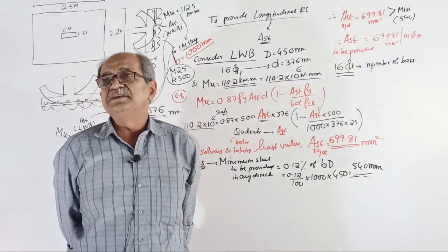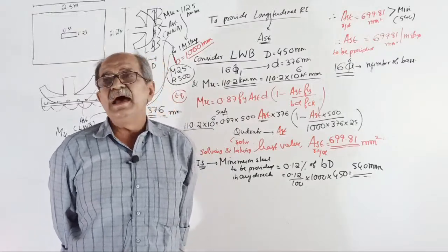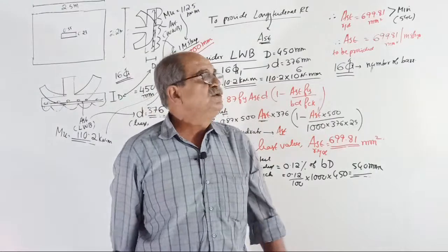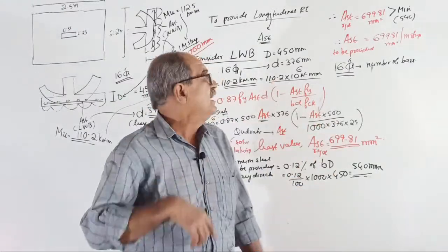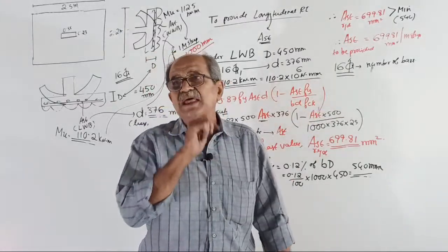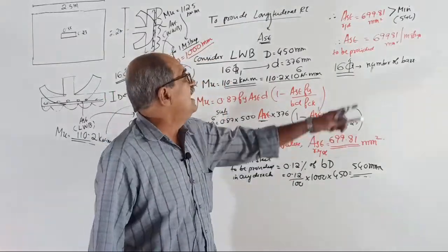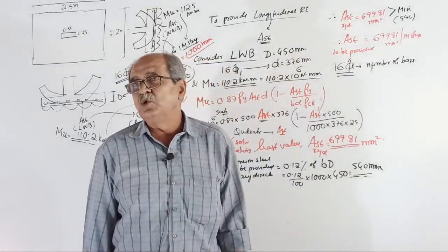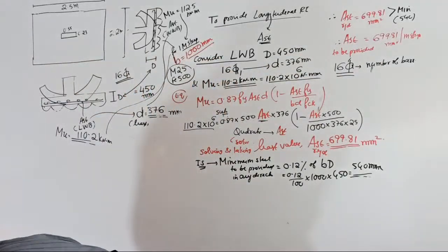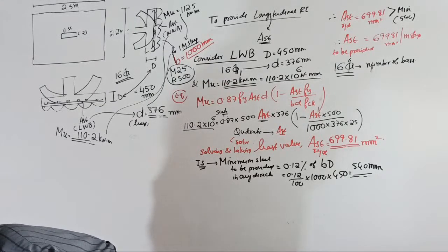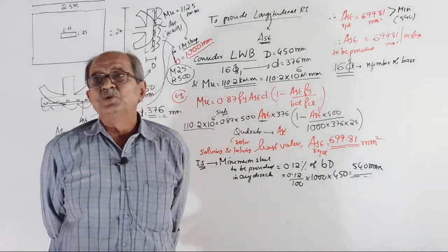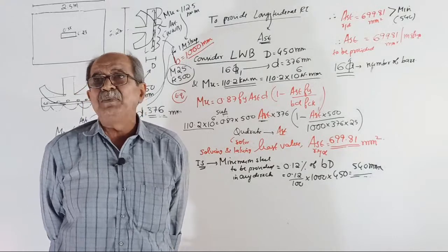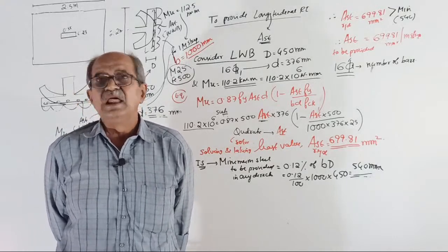Whenever you consider a strip in a slab, in case of beam, you don't take a strip. You take the full width, because with limited width you go for number of bars. But whenever a strip is taken, you should provide the steel within the strip. So you don't find number of bars. Whenever for design purpose you consider a strip, later SAFE also will give the same answer. Tell what you have to find.